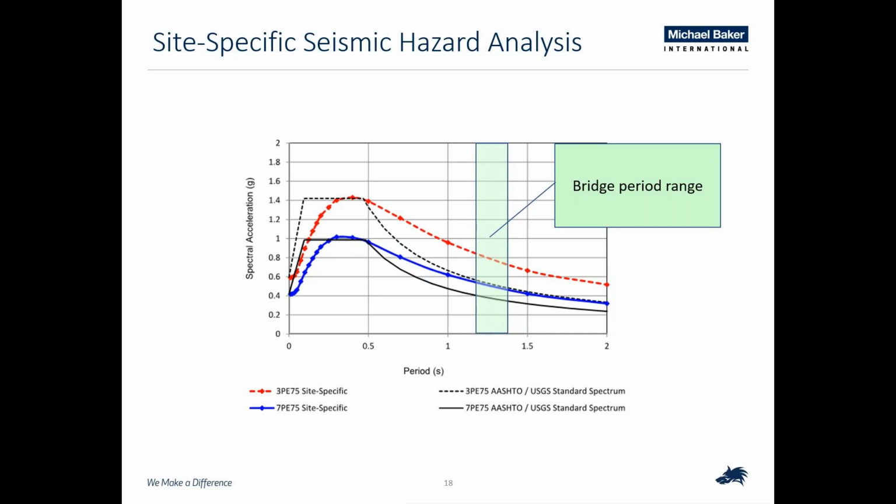exceedance. And so you can see the site-specific analysis does estimate higher spectral accelerations for the longer periods compared with the AASHTO standard. So it was good to see this, that it was good to do the site-specific hazard analysis to accommodate that probability.